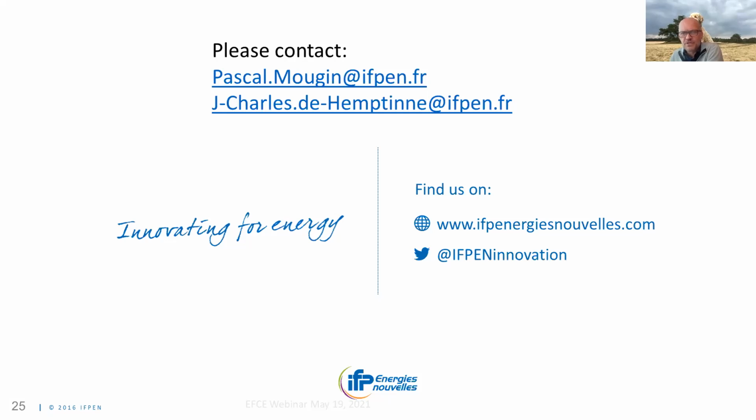Is there any recommendation, or do you have a suggestion, which property should be measured first for proper process development involving ELAC and CL? Well, what we have seen is clearly that the mean ionic activity coefficient is the most sensitive among all the properties. So I would really focus on that property, the ionic activity coefficient, because that has the steepest response to the parameters. So clearly that's my first answer.